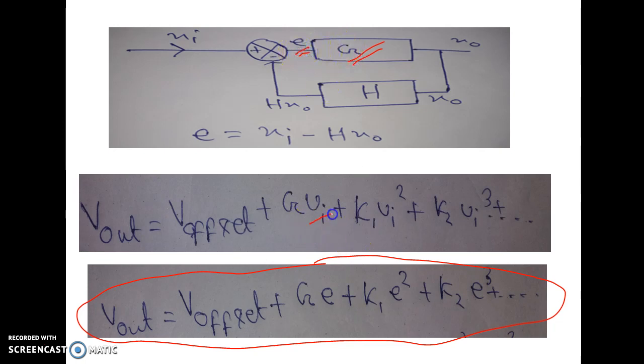So we can substitute the Vi by E, and we get V output equal to V offset plus G into E plus K1 into E square plus K2 into E cube plus dot dot. Clear? Now in the next step, what we can do, instead of E, we can substitute this expression, that is